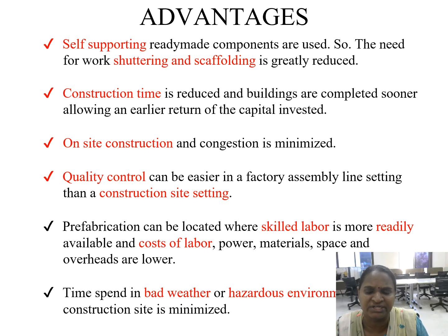Prefabrication we can locate where the skilled labor is more readily available and the cost of labor, power, material, space and overhead are lower. Time spent in bad weather or hazardous environment at the construction site is also minimized.